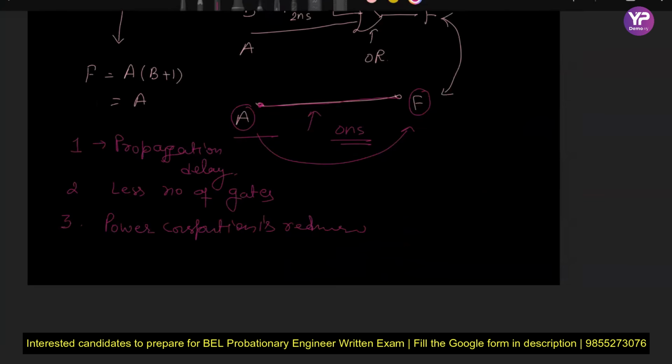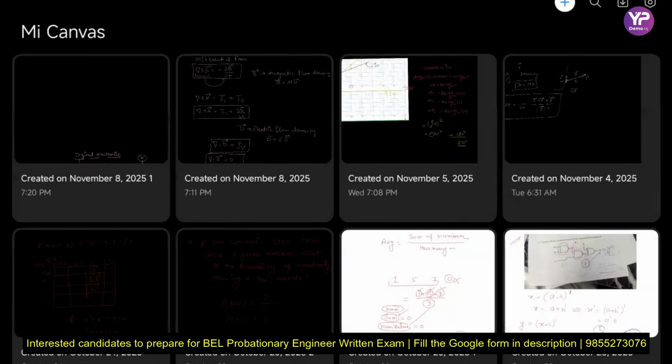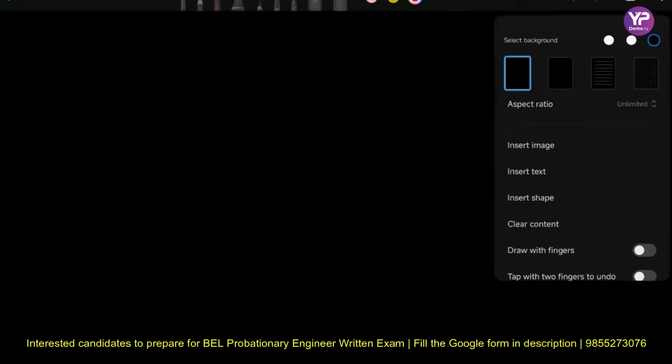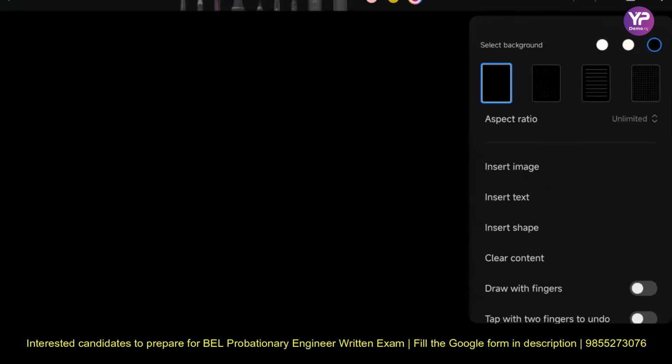So basically, whenever we are making any circuit, the first thing we do is try to minimize that circuit, minimize that expression. Why are we minimizing? So that after minimization the number of gates is reduced. As the number of gates is reduced, power dissipation will reduce, delay of the circuit will reduce, complexity of the circuit will reduce, cost of the circuit will reduce, right?